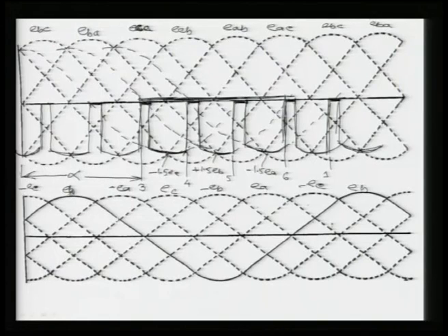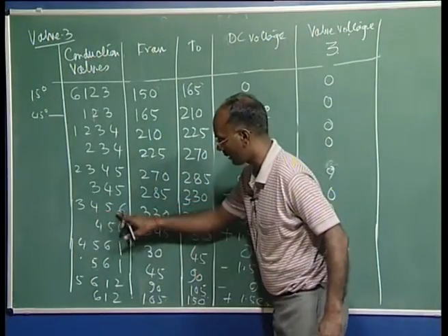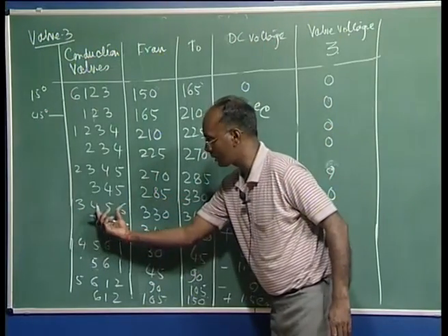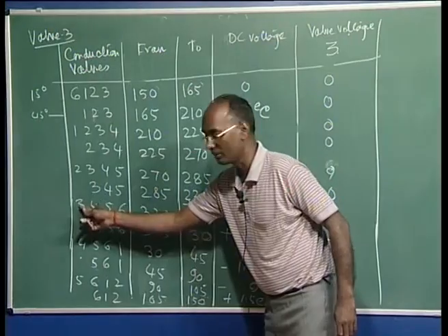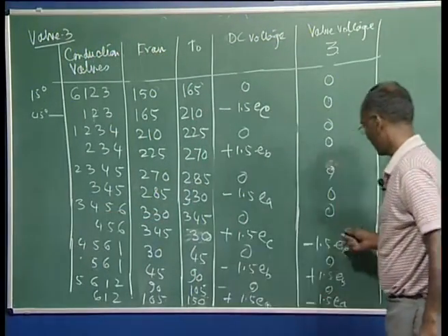So it will be going up to this portion as well. Now I draw up to here when 3, 4, 6, because 6 is getting pulse, and for this duration again this 3 is there, because the commutation between 3 and 5 is over now. So, we have reached up to here.